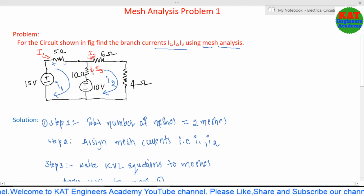I3 is given in the downward direction. You consider small I1 as the reference, so I3 equals I1 minus I2. Like that, you have to determine the branch currents. Whenever you are solving a problem by using mesh analysis, first you have to identify the mesh currents, then according to the question given, you have to solve the problem. In our question they are simply asking what is I1, what is I2 and what is I3, which are branch currents.